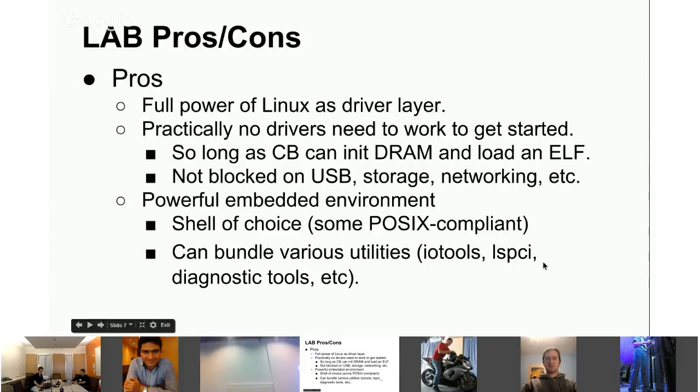Like iotools is this nice little thing that we have. It just pokes and peeks at registers and whatnot. And you can also bundle things like flashrom and just any number of diagnostics or utilities that you might want to write for a particular piece of hardware.